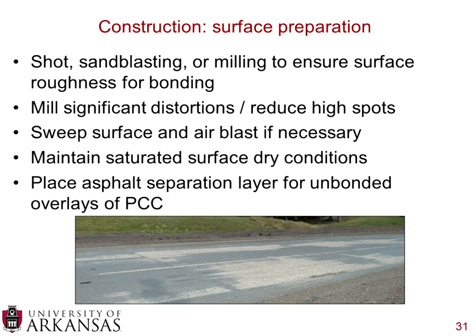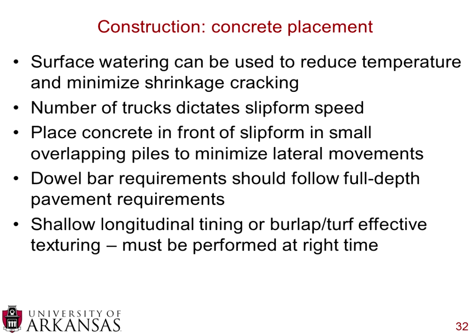And obviously if you're going to use your unbonded PCC on an asphalt, or if you're using your unbonded PCC on a PCC surface, you want to place that asphalt separation layer down beforehand.